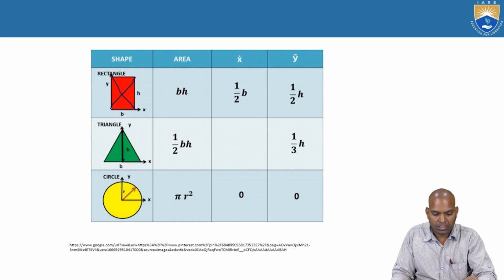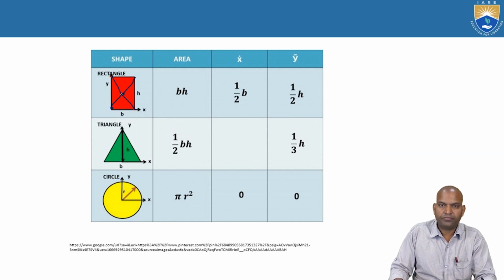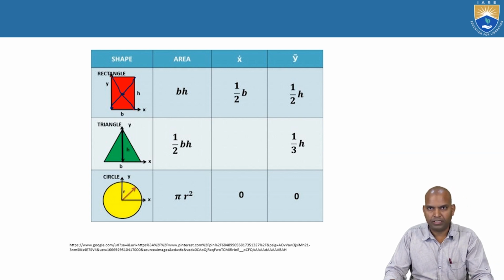In the case of the triangle, based on the reference axis, it is symmetrical about axis y, so the centroid will be on the symmetrical axis, that is y-y here.